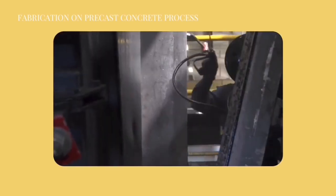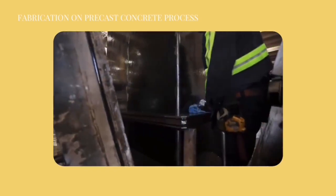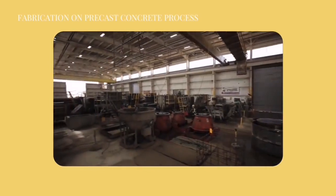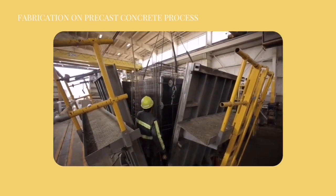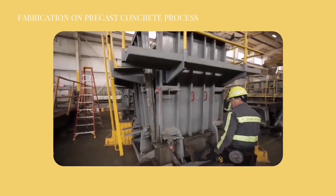Then a form release is applied to each surface to ensure the final product can be easily lifted from the form. Now that the form is prepared, the overhead crane is used to pick and place the cage onto the core of the form. Care is taken to ensure that the reinforcing cage is stable for transport to the form.